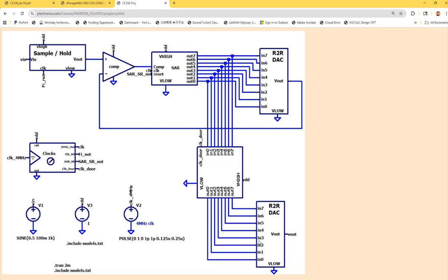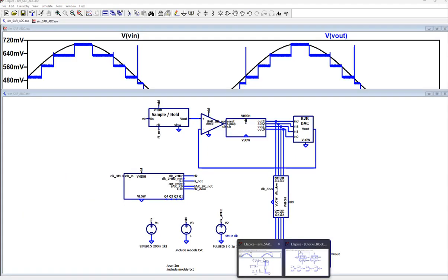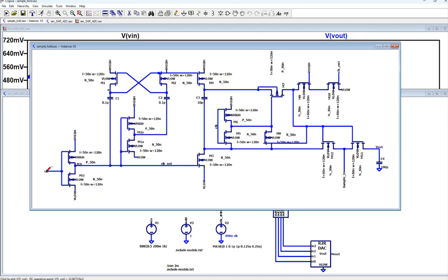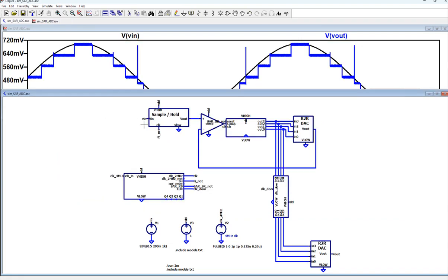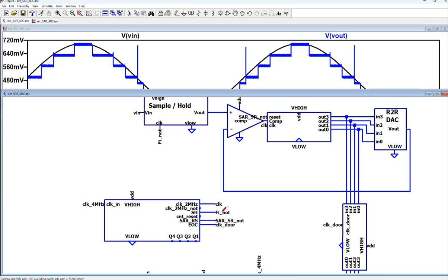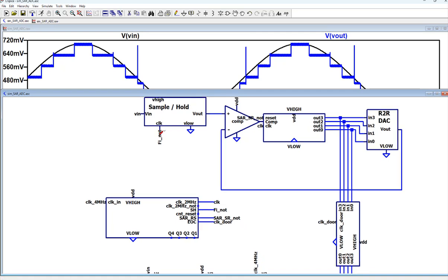You see, sample and hold has a clock. Do you know sample and hold has a clock? I think so. Yeah. What's the clock? It's over here, right? Remember? We talked about that, right? It has a clock, then it samples, right? So there's a clock for sample and hold. So we need that clock to be here first, which I named phi naught, which is this guy. That's a phi bar, shown on the schematic, but it's just a clock. So this clock comes in, you need the pulse first, right? Pulse, and then the falling edge will hold it.